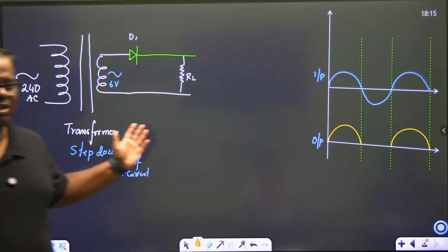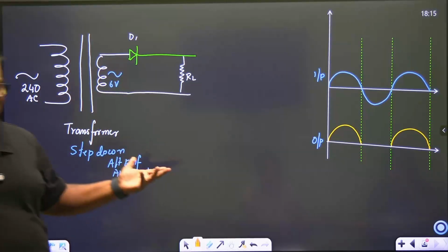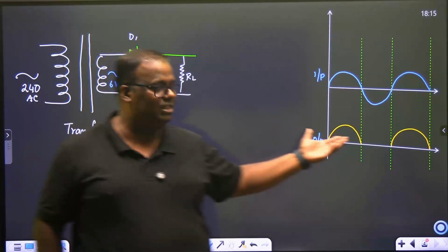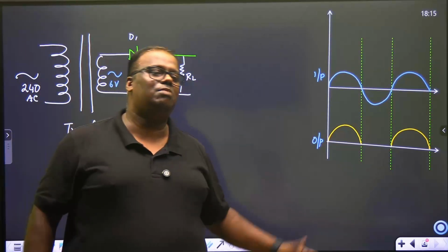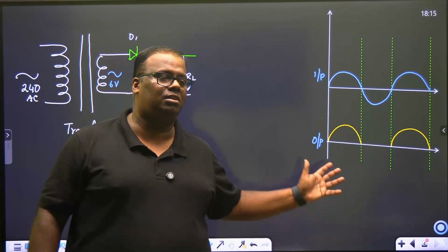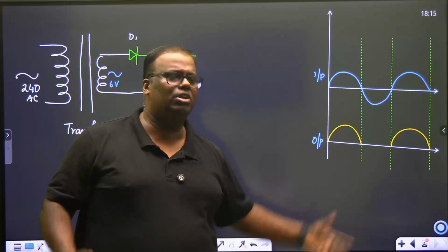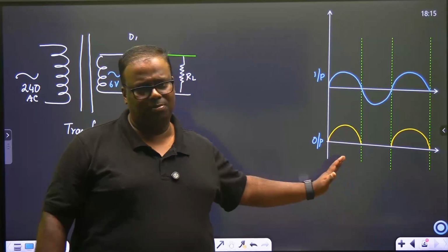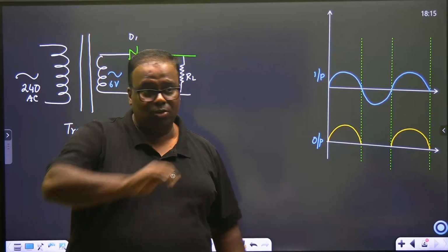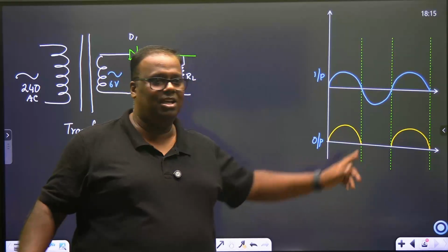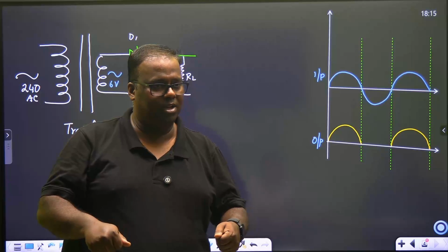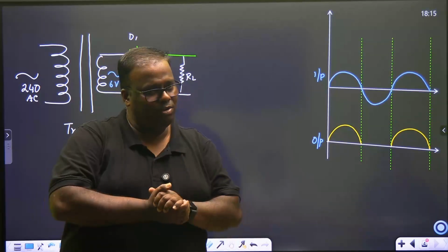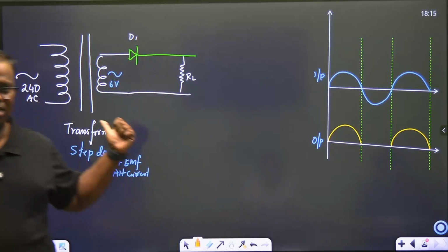This is half wave rectification. But this is not doing our job. In fact, if I connect this to any speaker, you know how the speaker will sound? The song will come, but the speaker will keep on humming. So it won't work, our work isn't getting done with this. We need steady DC. This isn't steady. It's coming in that manner. Ready for full wave rectification then? Have you understood what is half wave rectification?